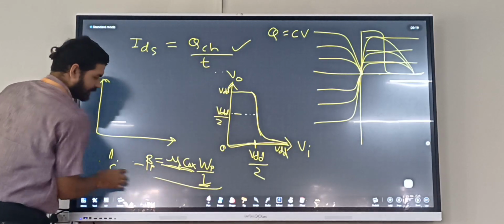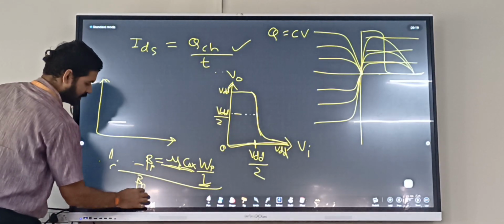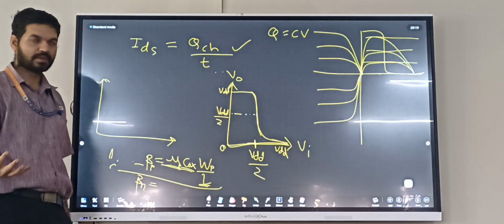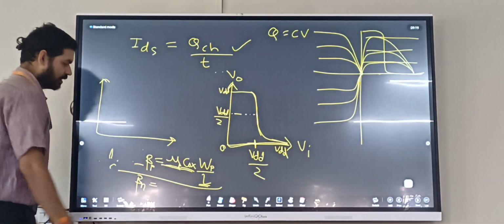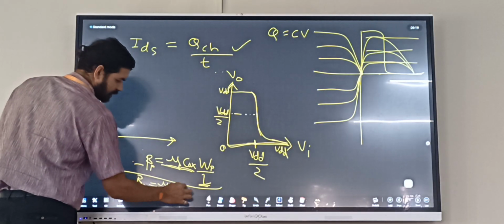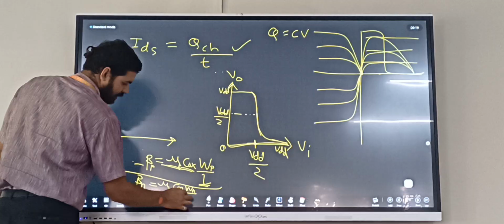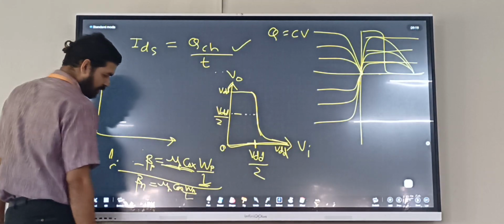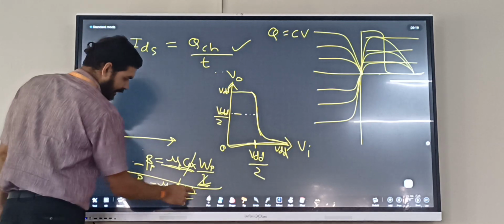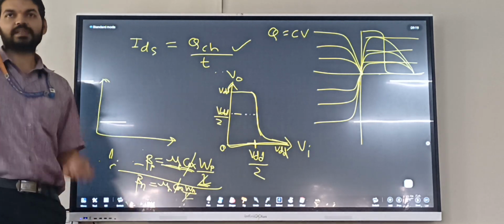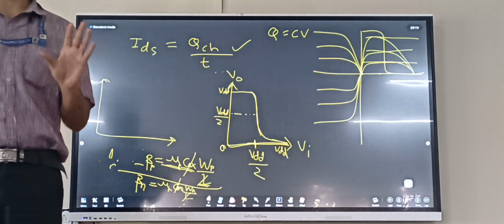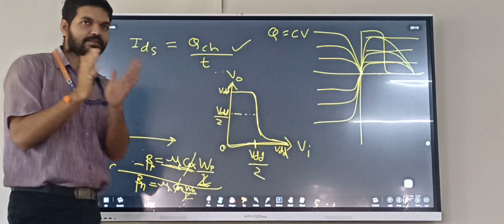And if I divide this, say by beta n, it is beta of NMOS. This is beta of PMOS. So I'll write here mu of n, then COX, then W n divided by L. Okay, so COX can be cancelled. L can be cancelled because L for PMOS and L for NMOS is the same. We just play with only W. Width doesn't change, what you know.